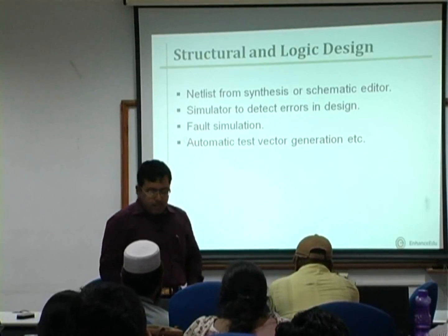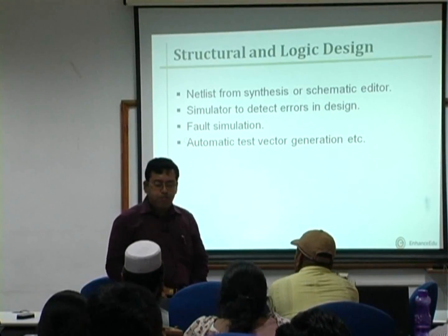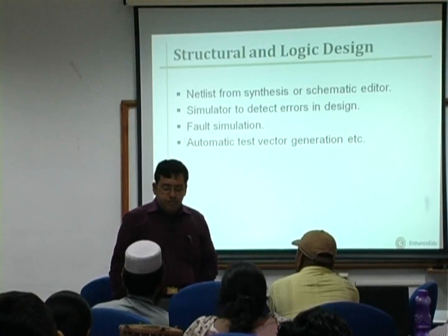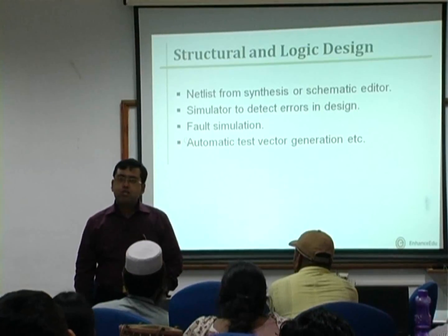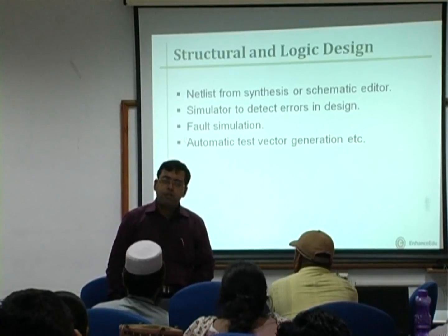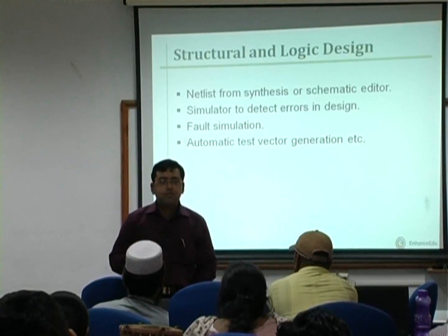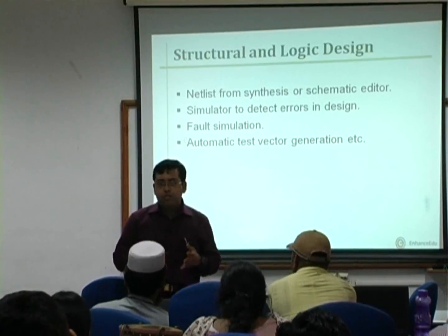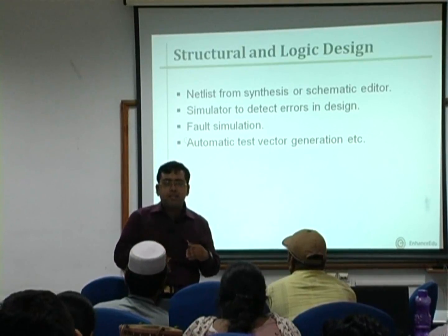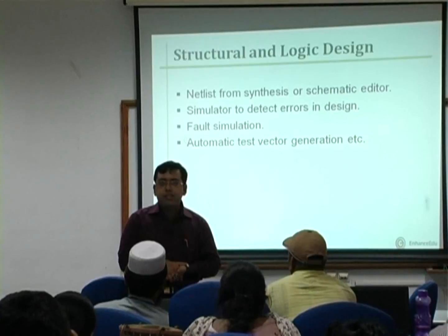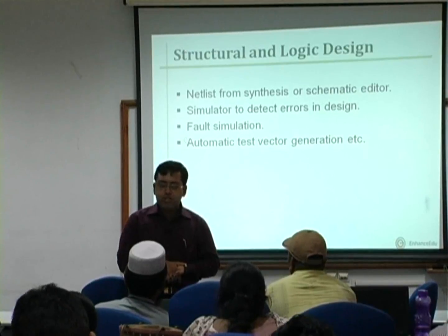So for that we do the popular fault simulation, and in fact we also incorporate certain components in the circuit called built-in self-test components. They generate various test patterns to exhaustively test the various logic in the circuit.